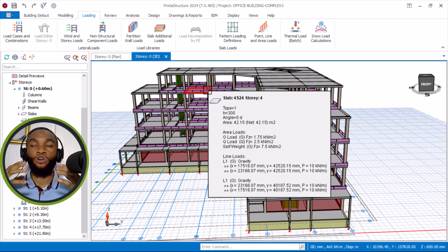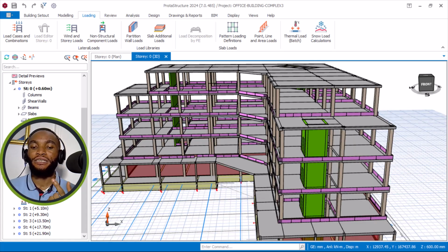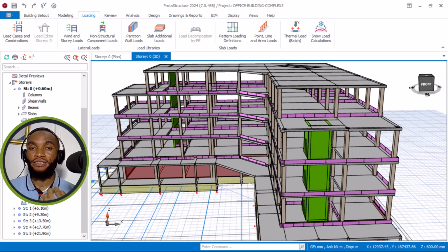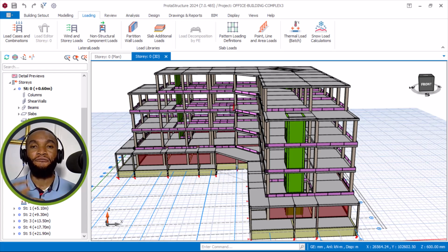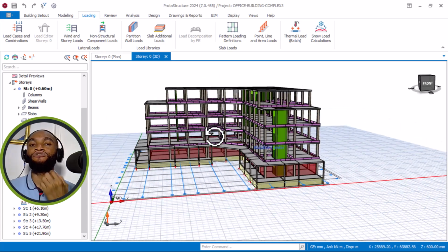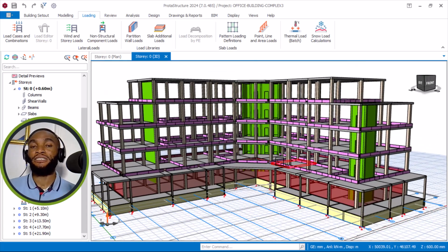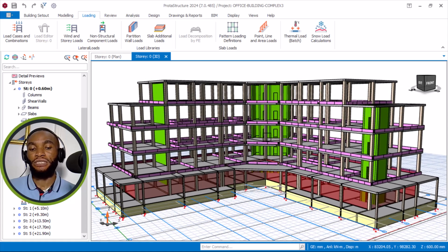Now, once the joint fails, every other member connected to that joint will also fail. So that's why joints between column and beam are a vital case you must deal with. The confinement around the foundation is a vital case you must deal with. If you don't have confinement, you must introduce confinement around the base. Well, that will be a different seismic design altogether.